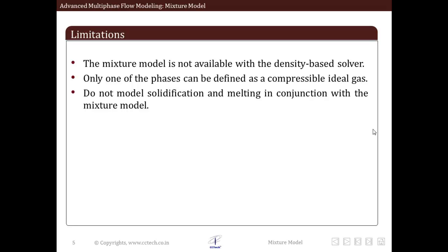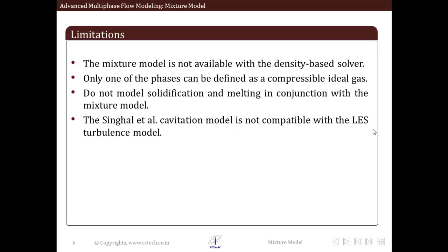We cannot model solidification and melting in conjunction with the mixture model. The Singhal et al. cavitation model is not compatible with the LES model of turbulence when we use the mixture model. That is, when we activate the mixture model, we cannot use the Singhal et al. cavitation model together with the LES turbulence model.